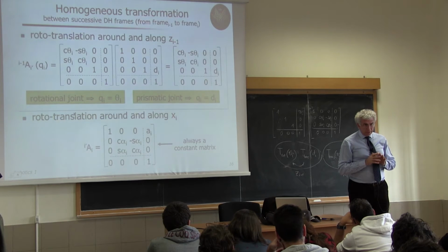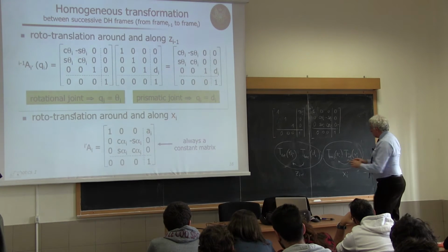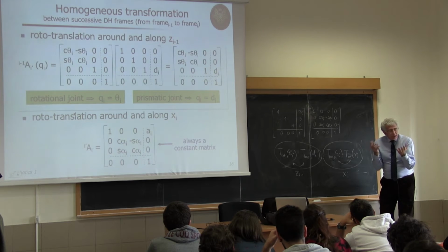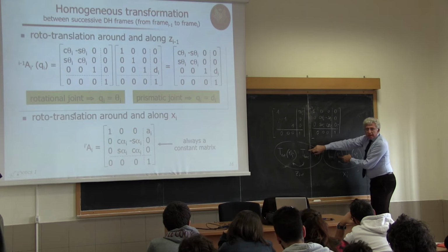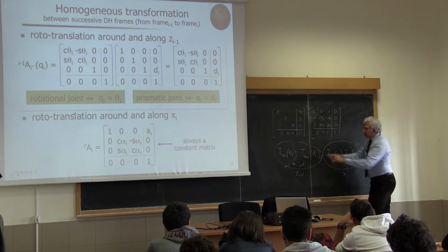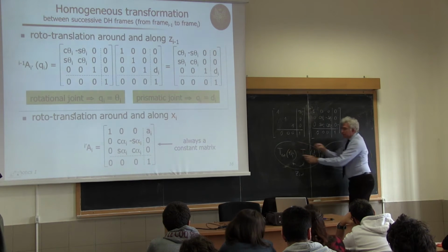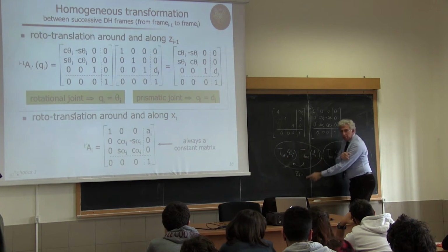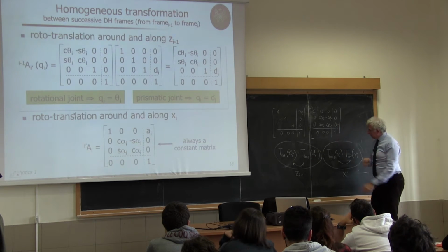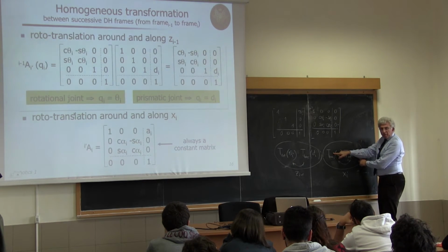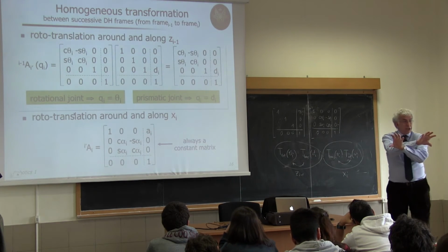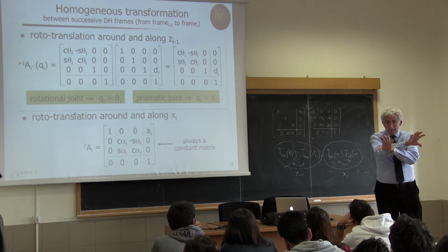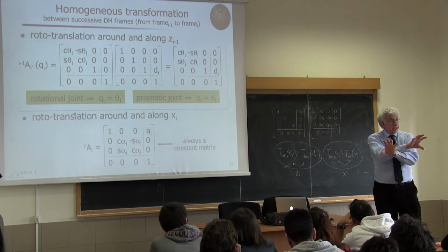Rotations do not commute, so there's no sense in doing this; it's just an exercise in reasoning. I could exchange this with the translation and I would obtain the same result. What I cannot do is exchange the two rotation matrices once they are contiguous, because they are not around the same axis. Then I will make a mistake.